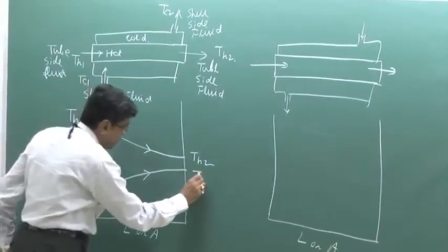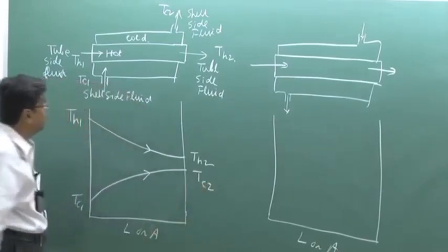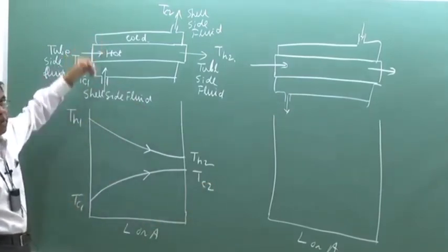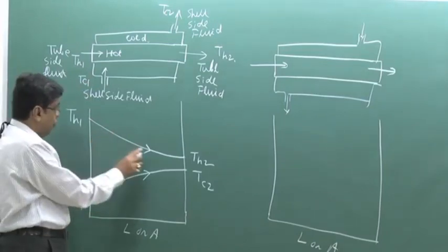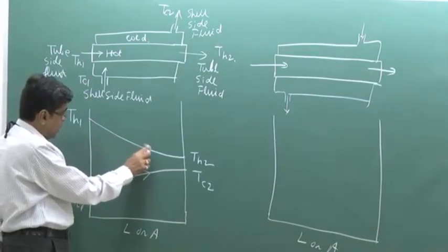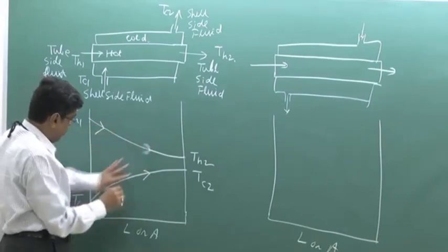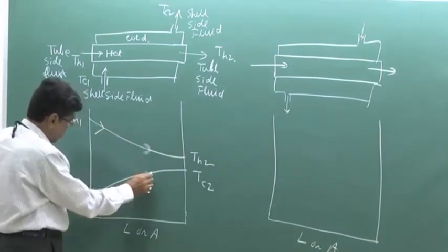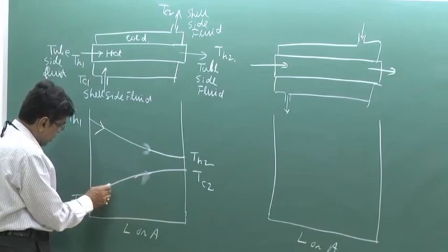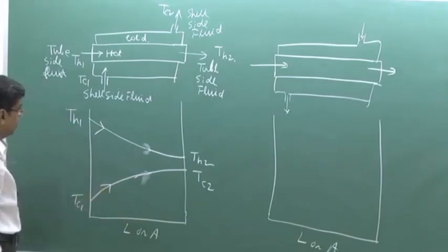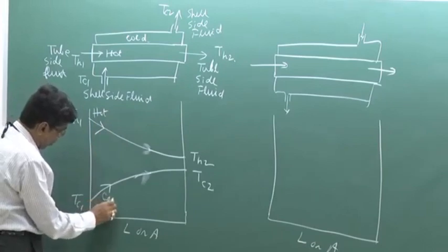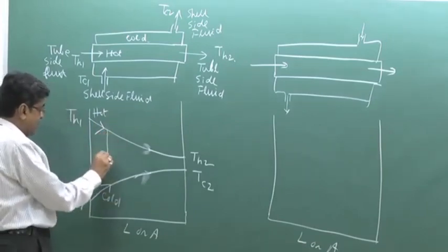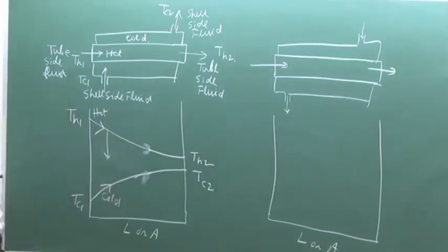This is the picture. The assumption is that the fluid temperature is uniform across a section. This is the hot fluid, sorry, I should show this arrow here, I will draw it differently. This is the cold fluid, this is the hot fluid temperature diagram, this is the cold one, and at any section the heat is flowing like this from hot to cold.